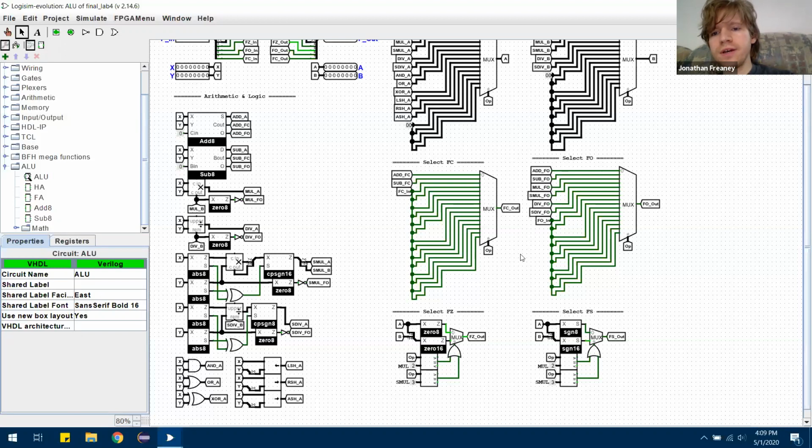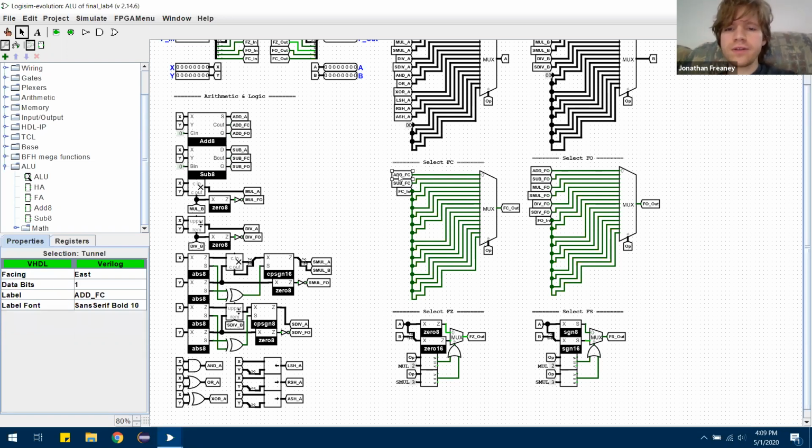You could also use it for division if you end up with a divide by 0 error, which is what I've done here. But we also use it for addition and subtraction, because over here the carry bit stores the result of unsigned addition and subtraction, whereas over here we reuse the overflow bit to indicate whether there was a carry for signed addition and subtraction.